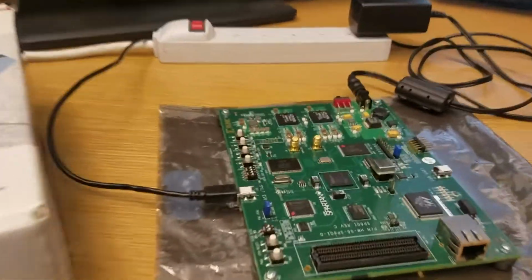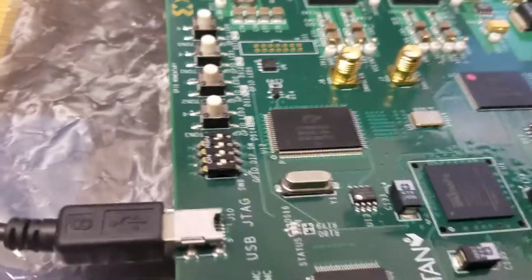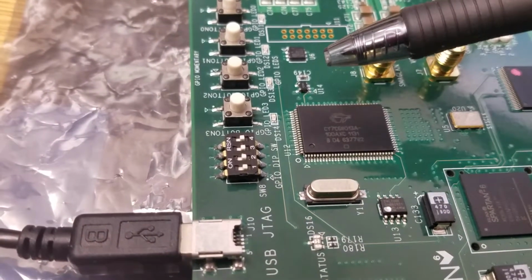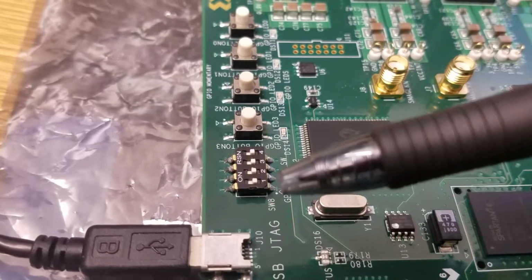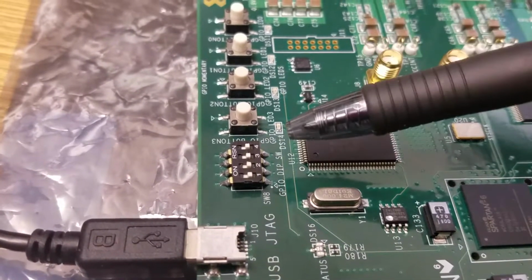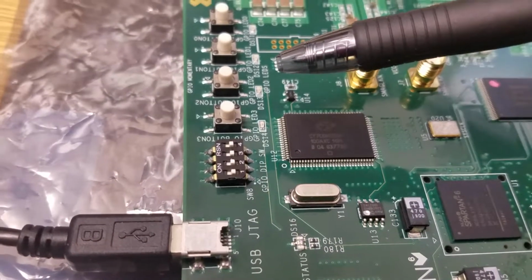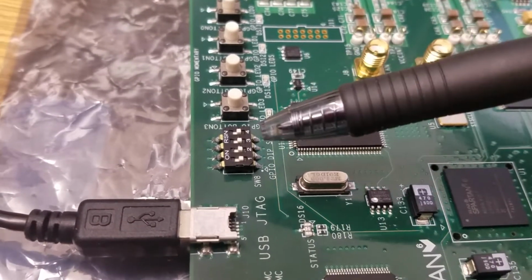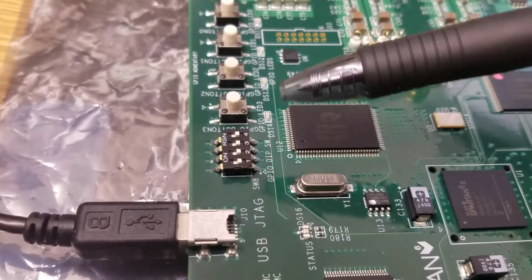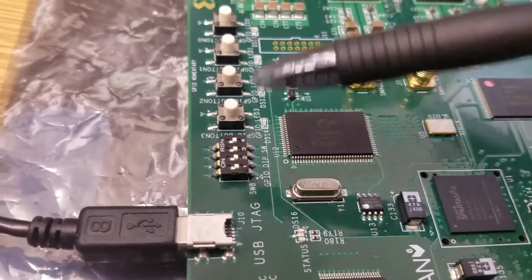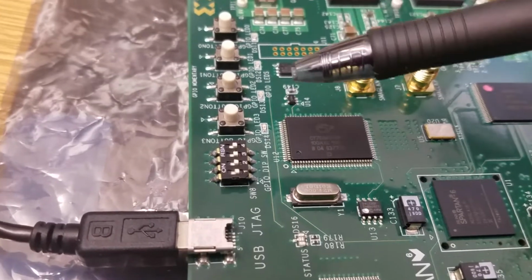The goal of this simple exercise is to use these dip switches right here so that whenever you turn them on, they turn on these LEDs respectively. Let's say switch 1, if you turn it on, turns on this first LED, switch 2 turns on the second, switch 3 turns on the third, and just to change things up a bit, switch 4 will be a reset. So no matter what these states are, whether the LEDs are on or off, if you turn on switch 4, it resets and all the LEDs are turned off.